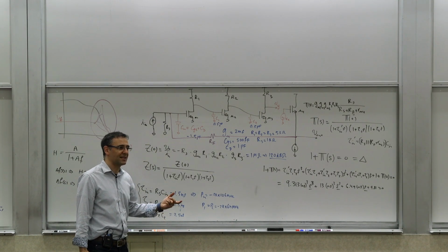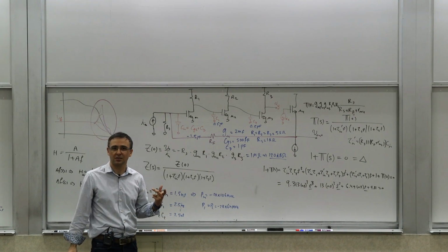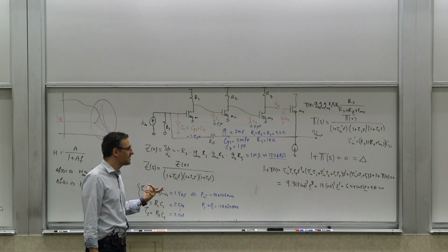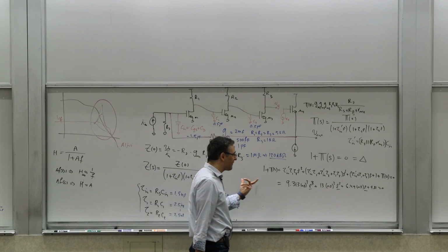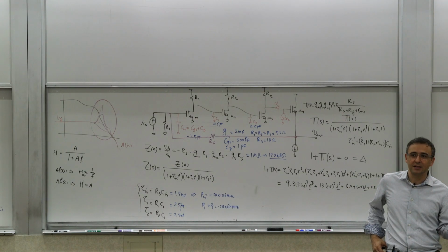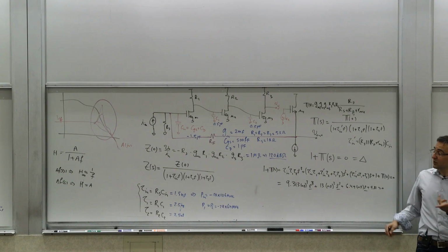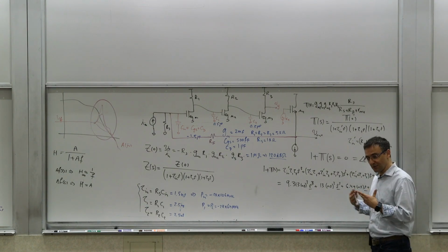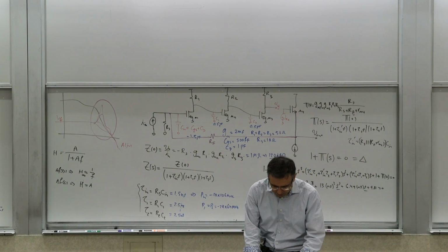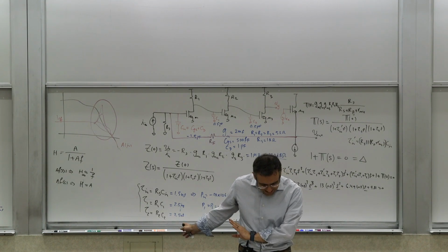There are numerical methods, like the Routh-Hurwitz method, that we'll talk about briefly next time, to determine where this is. There are also graphical methods where you can actually plot this, and by looking at the plot, you can see where it is, like the Nyquist method. And this is for linear, and then for nonlinear stuff, there are also methods that have been developed, which are quite remarkable, that actually you can have general methods for nonlinear stuff too. But that's a pathway we'll take.